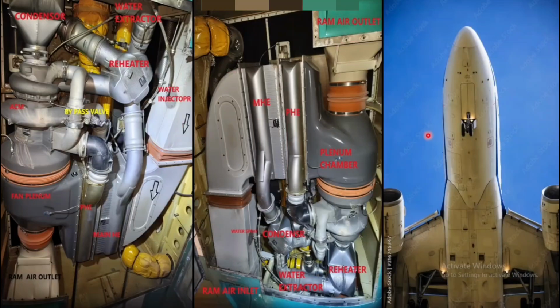So this is your ram air inlet. Then water spray, if you see from this inlet area, you will get water spray. You can see water spray is going to the water extractor. This is your water extractor, this is your reheater, this is your condenser, this is your plenum chamber, and here you see the fan rotating, and this is your primary heat exchanger, main heat exchanger. I told you about the bypass valve. This is your bypass valve, which goes to mix into the turbine section. So this will reduce the temperature. Any component left? I have almost covered everything.